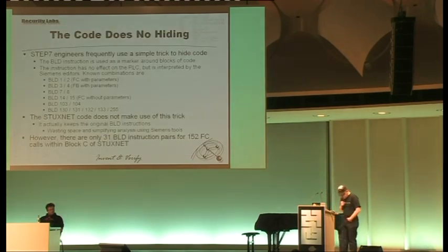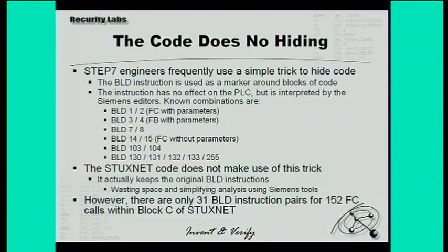What's interesting is that there are a number of interesting hacks that you can do with an instruction called BLD. The BLD instruction actually does nothing on the device. The PLC is just going to ignore it. It's like a NOP, but less so. What it is actually used for is by the compiler to mark the complex calls.